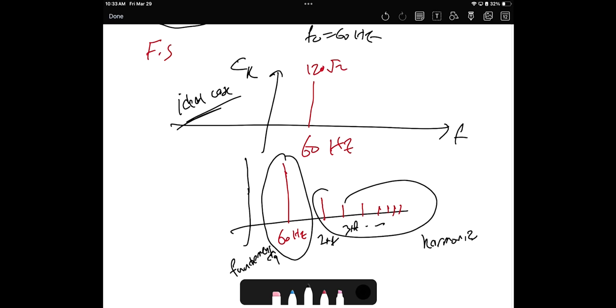Other sources of the harmonics are renewable energy sources. How? The photovoltaics generate electricity as DC. Right? We need to convert DC to AC, so we can use it. To convert DC to AC, I'm using electronics. I need to use inverters, which are based on MOSFETs or transistors, or IGBTs, whatever. Then, when you use electronic devices, you are creating harmonics. So the renewable energy sources' interaction with the grid causes problems.